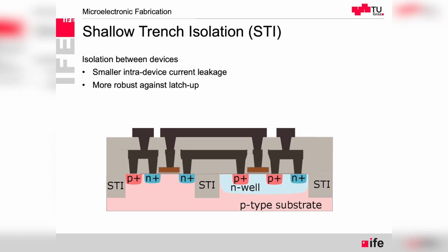The next improvement that I would also like to point out in a dedicated slide, that's something that is a norm nowadays, but it didn't used to be, is the shallow trench isolation. So what we have seen in the previous slides, very often I drew PMOS and NMOS transistor in a single die, and then there was nothing in between. That was a simplification. For years, we had a so-called LOCOS, which was an oxide layer, which was not really good for planar realization of the circuit.